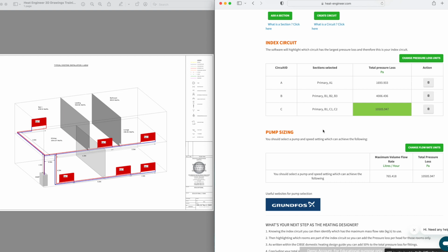If you've got a plated heat exchanger or a secondary heat exchanger, some hydronic separation, whatever it is, if you've got additional pressure losses within those, you'll need to refer to your manufacturer's instructions or speak to the manufacturers and find out what the resistance ratings are of those heat exchangers, and then you add that to the total amount of pascals that you get within your primary circuit.